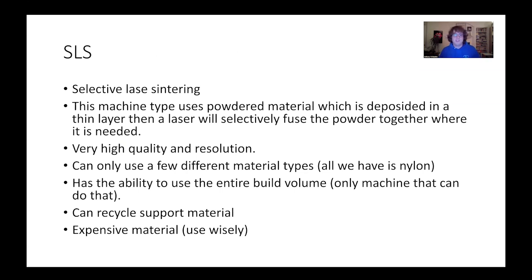Okay. Finally, we have selective laser sintering. Ours is a plastic laser sinterer, but there are other ones that sinter metals and things like that. Basically you have a layer of powder that's set down on your build platform, okay? And then a laser binds together all of the portions that will later become your part, and then it lays another layer, okay? Critically, it doesn't do anything to take away the loose powder that was non-sintered, because that becomes your support material.